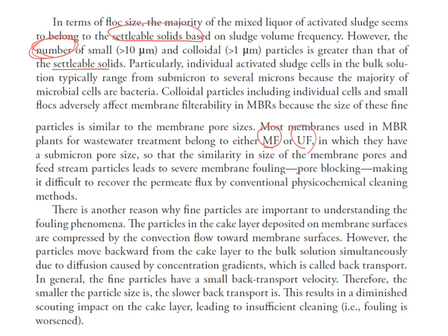So pore blocking may happen, which has a more severe impact on the membrane performance, and this will cause more severe membrane fouling. There is another reason why fine particles are important in the fouling process.